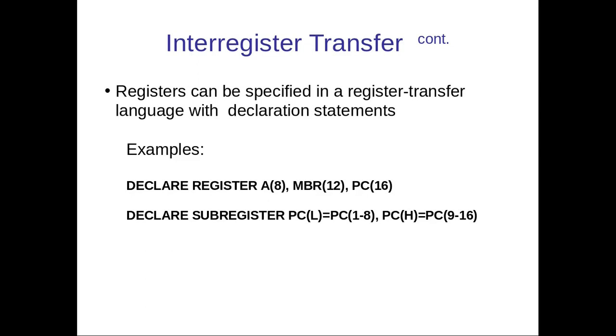This register transfer language specification can be compiled by using special compilers that will translate these high level statements into flip-flop or gate level, or register transfer level circuits. That file can be given to a fabrication lab, and we can easily fabricate our digital system or ICs.